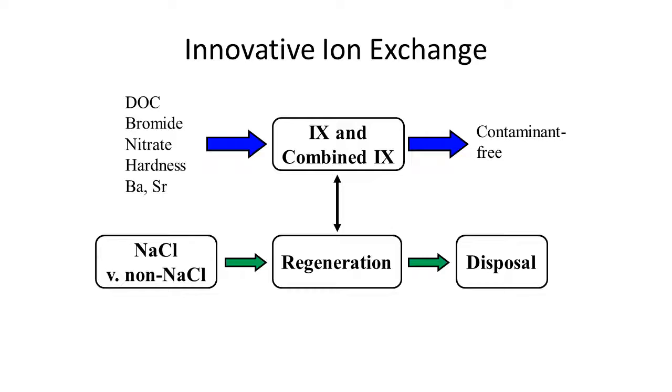That is really thinking about the regeneration process. Here, the way we refer to it is sodium chloride versus non-sodium chloride. And we've done a lot of work thinking about what that non-sodium chloride can be. We've explored potassium chloride, sodium bicarbonate, and potassium bicarbonate. I'll show some results from the life cycle assessment that's helped us refine that thinking. But what we are moving forward with is of course NaCl, because there are reasons why it's widely used. It's cheap and it works.